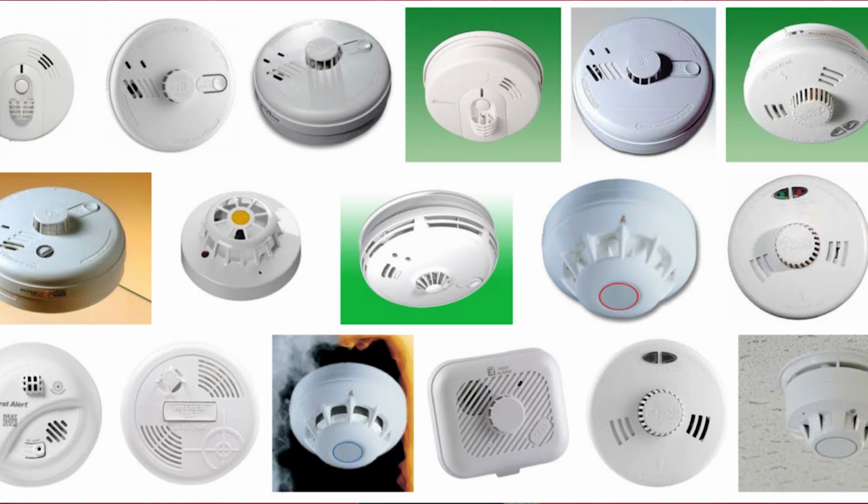There are both hardwired and battery-operated heat alarms. Now, to test a heat alarm, you need to do the push-button test. As there is no product available to create excessive heat except a fire, you'll be unable to test the function of this alarm apart from a push-button test. The main visual difference between a heat alarm and a smoke alarm is the small cage or dome which sits on a heat alarm. Smoke alarms tend to be flat on their casing.